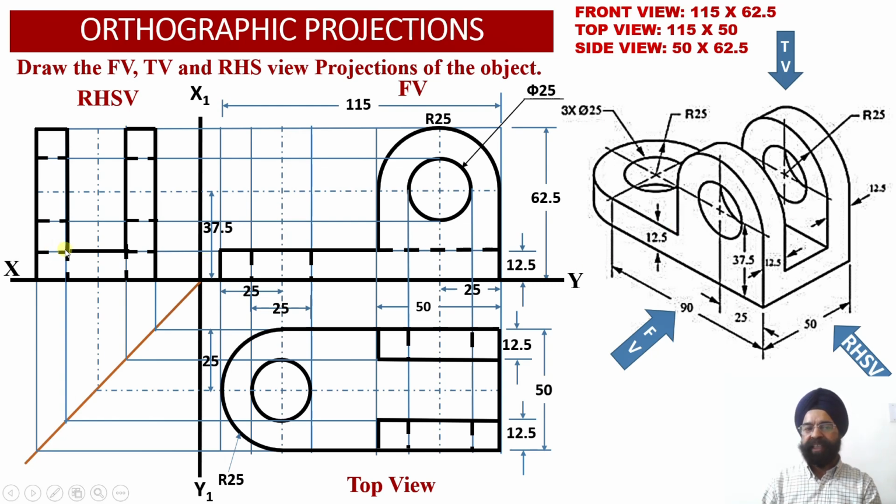That is the thickness of the web, so this will not be visible to the observer, as the observer looks at vertical web number 1 and vertical web number 2 from the right hand side. So that is why one hidden projection line corresponding to the top surface, the 12.5 millimeter thickness of this vertical web, is not visible to the observer from the right hand side position. So hidden line projections will be obtained over here.